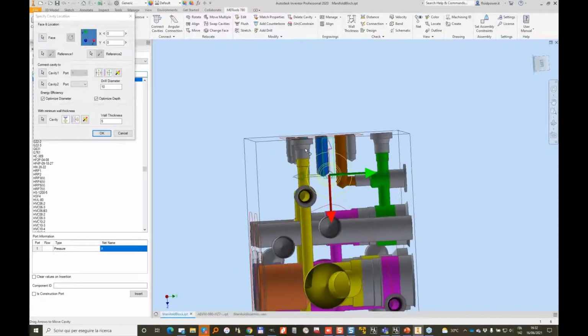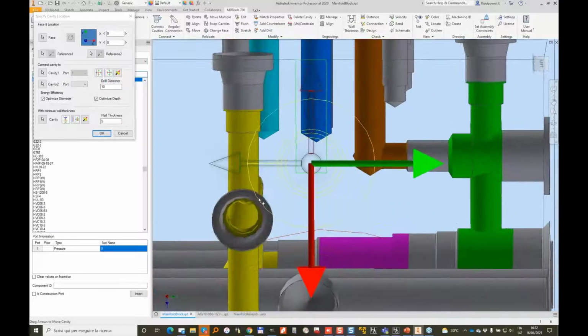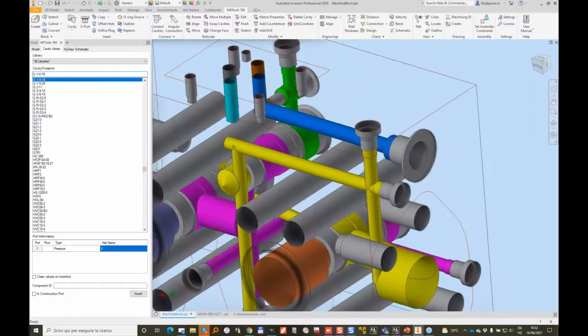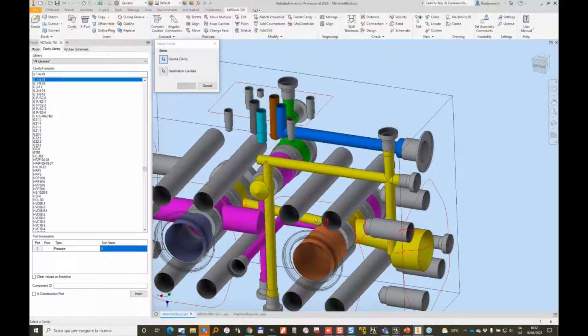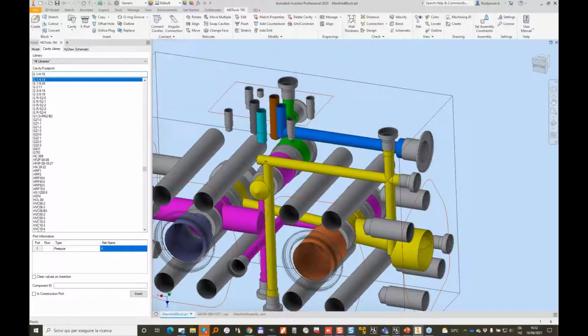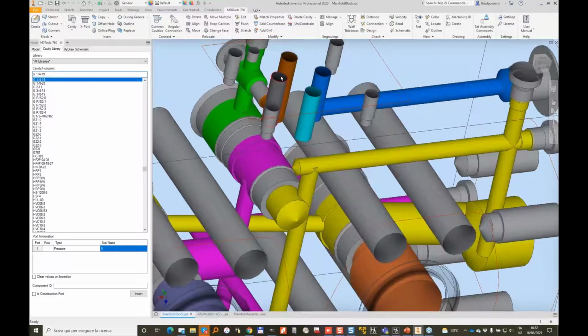Connected to this port. There is an overlapping of spot face. Let's move it slightly up. No overlapping. We could also move slightly left or right according to how you want. Let's stay with a 7mm diameter. No, we used the 6. Let's keep the same tool. Match property. This tool with this one, we want to copy the same drill diameter. So now when the manufacturer will machine this face, with the same tool, it will make also the other drill. B port is not needed, so we can delete it or suppress it as you want.